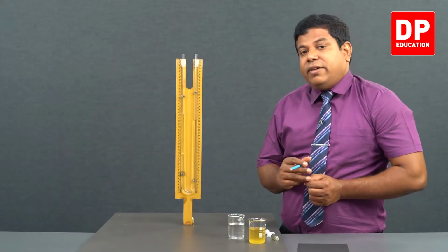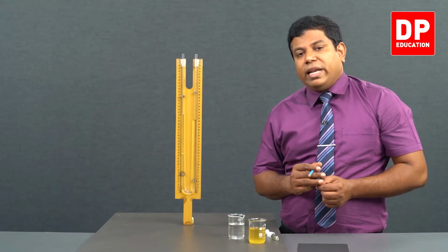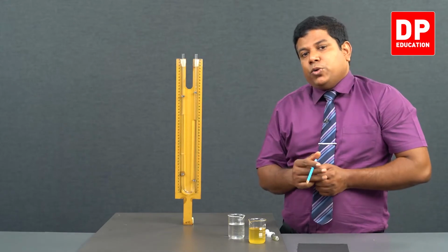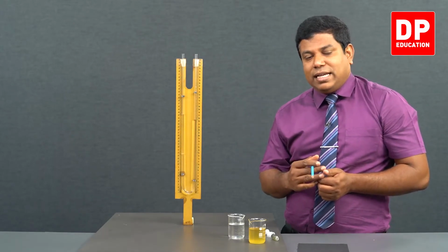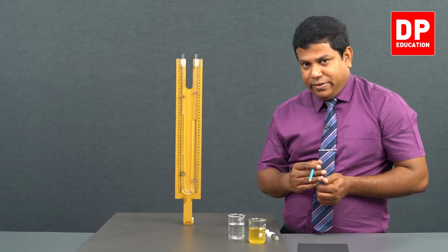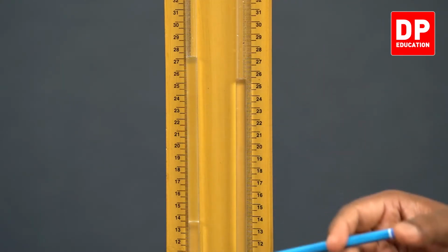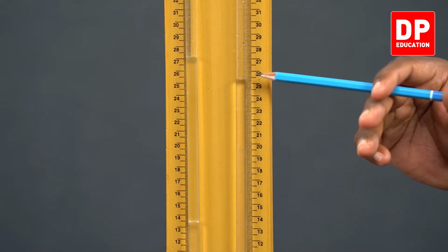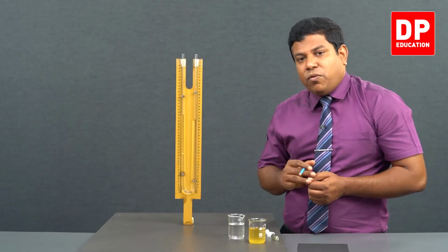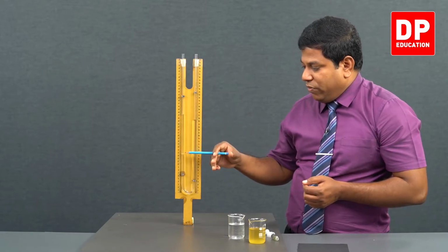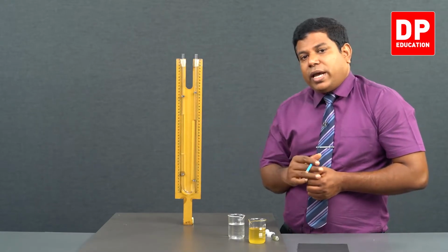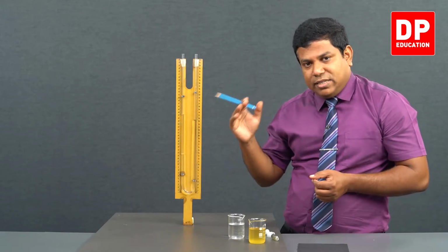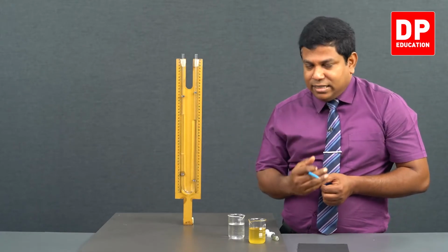The interface level is at 13.5 centimeter. Water oil interface is at 13.5 centimeter. And the oil level, you can see here, it is at 27.2. 13.5, 27.2 means that is 13.7 centimeters height. So if you get the difference, 13.7 centimeter is the height of oil. And the height of water, the reading here is 25.4 centimeter. So 13.5 is the interface, 25.4, so that is 11.9 centimeters height of water. So that is what HW and HO we get as the second set of readings.